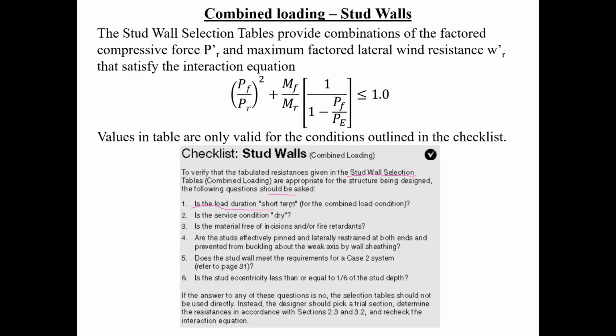Is the load duration short-term? Short-term for the combined loading conditions. The answer is yes, because the short-term load they're talking about here is the wind, and wind, of course, is a very short-term load, two to three seconds at most. It's less than seven days, no problem.